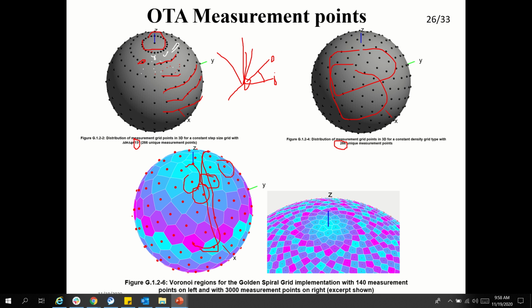If you are measuring from the antenna perspective, then you calculate derived parameters like gain, EIRP, whatever you want. So that is how it will look. You can see these mesh points here, and you are measuring this point. For example, if this beam is activated here, it shows dark pink color. Here it is not activated. If your beam is in this direction, it will have a certain orientation in both phi axis and theta axis. Then you can define that your antenna is radiating in this particular direction.